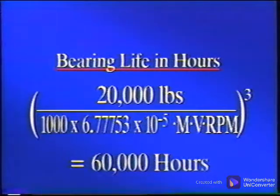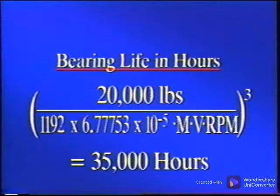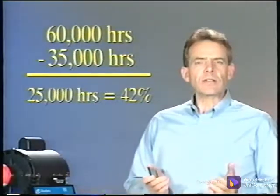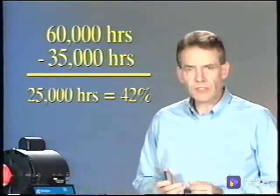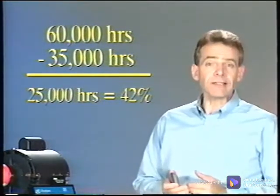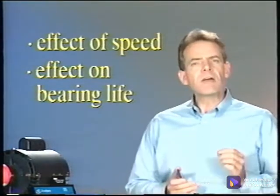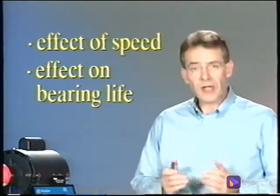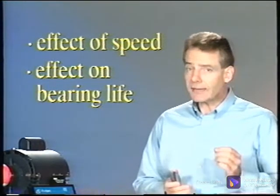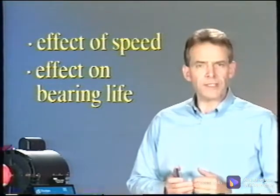When we add the 192 pounds from the effect of the unbalanced weight to the actual rotor weight and run the equation, the result is approximately 35,000 hours. The life lost due to the 1 ounce of unbalance is 25,000 hours, which is 42% of the original life. These two concepts, the effective speed and centrifugal force on any unbalance in a machine and its effect on bearing life, point to the need to perform quality balancing.